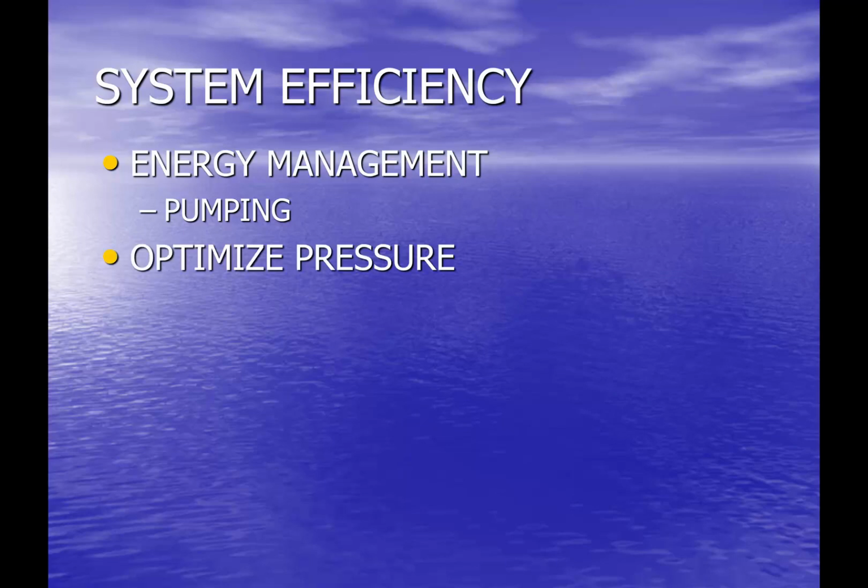Optimizing pressure. This is something that translates both into power or efficiency as well as into leak management. I've had board members ask me, hey, is there something we can do? Can we go with lower pressure that might require less pumping, that might produce fewer leaks? In some cases that's possible, but in others it doesn't work out, because again, remember, one of those core objectives is to maintain adequate pressure and flow. So reducing pressure to save money, you've got that same competing objective, efficiency versus maintaining adequate service.